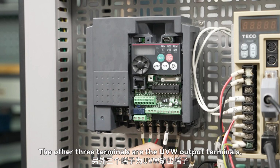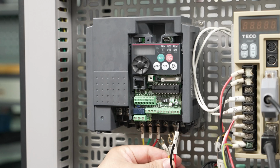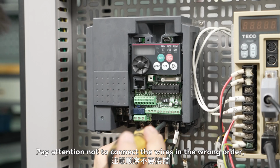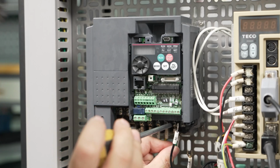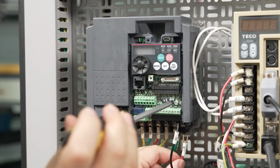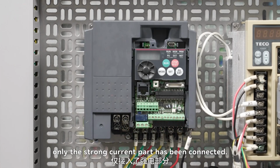The other 3 terminals are the UVW output terminals, that is, U, V, and W, which are connected to the AC motor. Pay attention not to connect the wires in the wrong order, and connect them in the order of U, V, and W. Currently, only the strong current part has been connected.